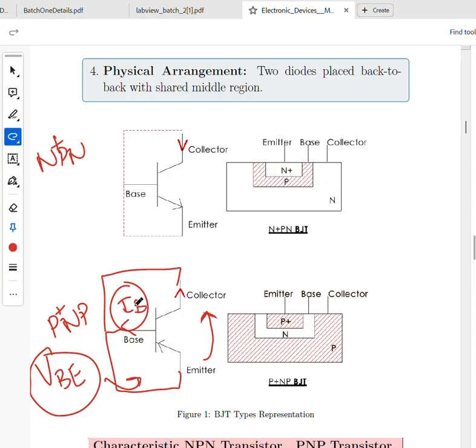A small change in this IB current will drastically affect how the emitter to collector current is flowing. So by tweaking the VB value or IB value, I can change how much current will pass from emitter to collector. It acts as a variable resistance here. This is why a small amount of current can drastically affect a much larger amount of current from emitter to collector. This gives you some feel of that amplification factor. I will elaborate on that in a moment.